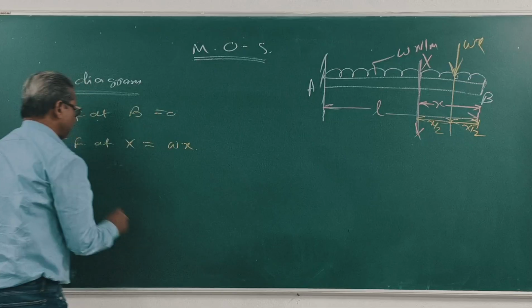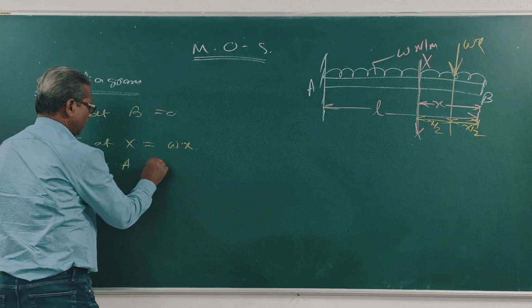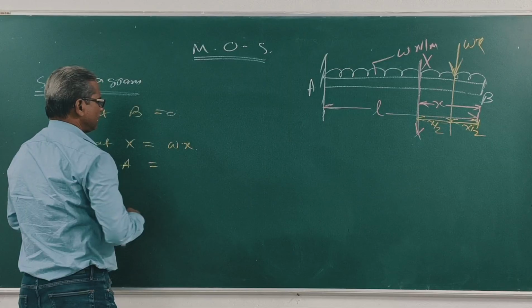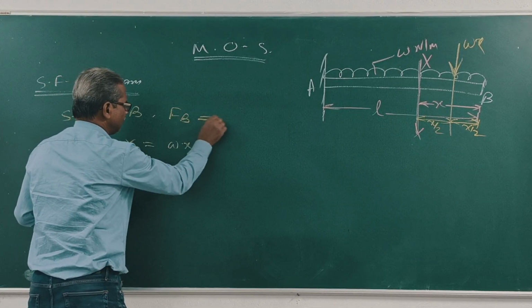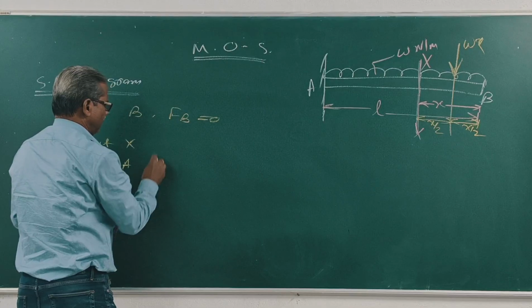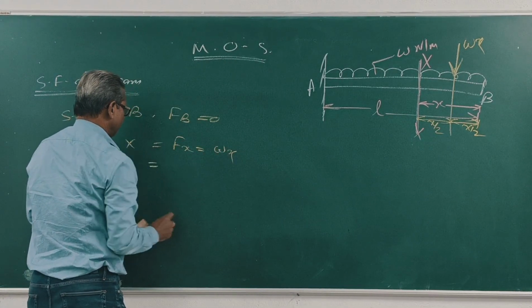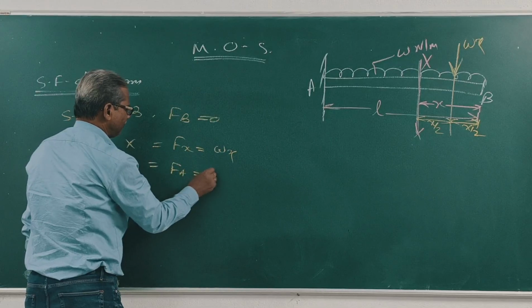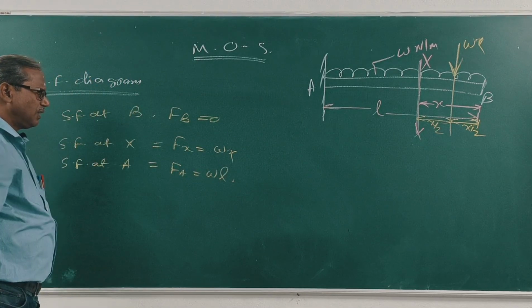Shear force at A: at B it is 0, at X it is w x, and at A it is w L. Right?